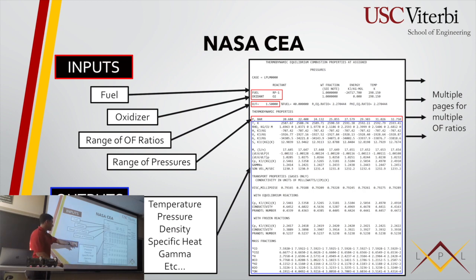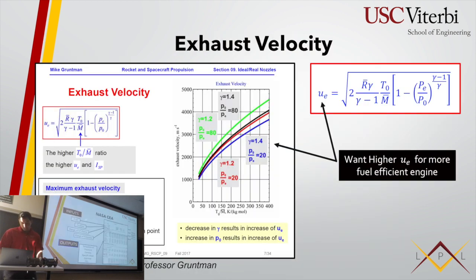So these are the things you care about at the end of the day. For your chamber, you tell it a pressure, but you end up receiving the temperature in the chamber and the density of your combusted gases now, right? So it's not just that you have some oxidizer, some fuel. What ratio it is, what density is that, what specific heat, what gamma, what ratio of those is it? And so this is pretty much all I'm going to be covering on the thermodynamics.